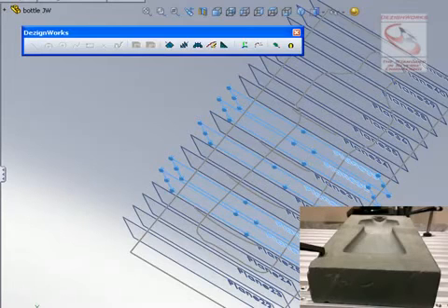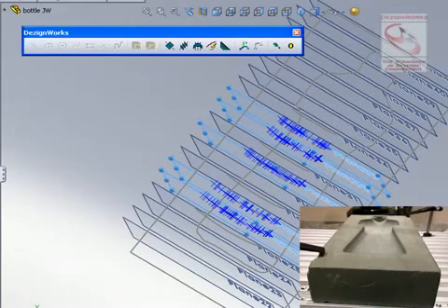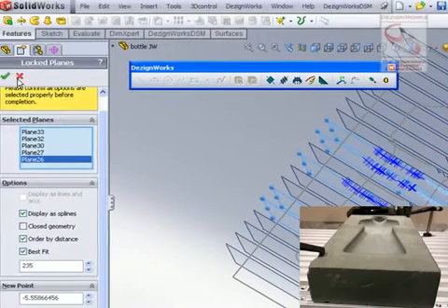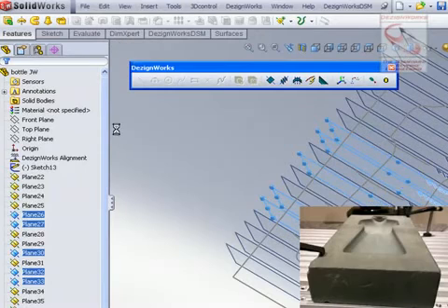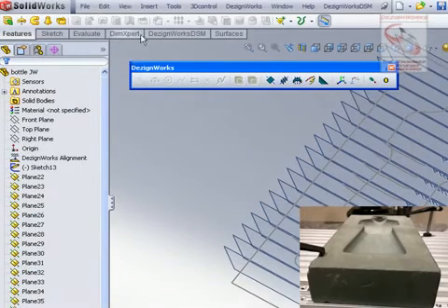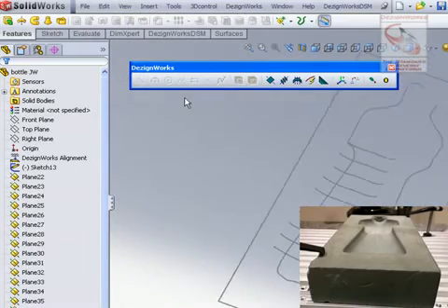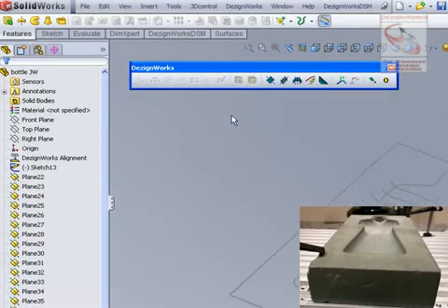The other nice thing is you can totally rerun the movement and actually say I want to change the spacing. So in this case we have the spacing of the points about every 1/8 inch. We could change that and tell it to freeform and rerun it. Now you'll notice more cross sections have been added to our model.